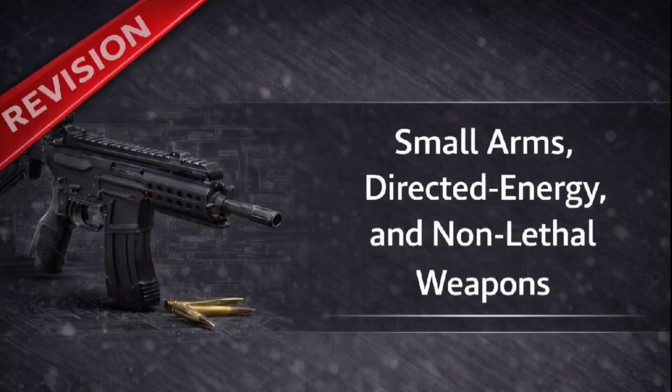I understand the location of that gas tap is a really critical engineering decision. Why does its position closer to the breech or closer to the muzzle matter so much? It's a major trade-off between pressure, heat, and fouling. Gas taken off near the breech is hotter and at a much higher pressure. Which sounds good. Well, the gas is cleaner because the carbon remains fully gaseous, which reduces fouling. But the high pressure causes greater erosion on the components, and it requires a heavier piston system to handle it.